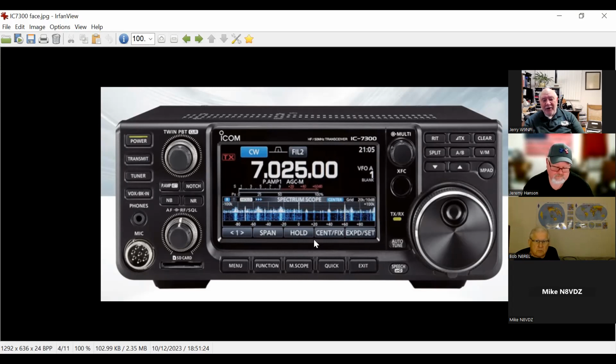But your best bet when you're buying one of these things, there's a company called LDG, and there's a Z100 model antenna matcher that they sell for less than $200, and it handles anything up to a 10-to-1 SWR, which I'd recommend. That's the one that I just got.